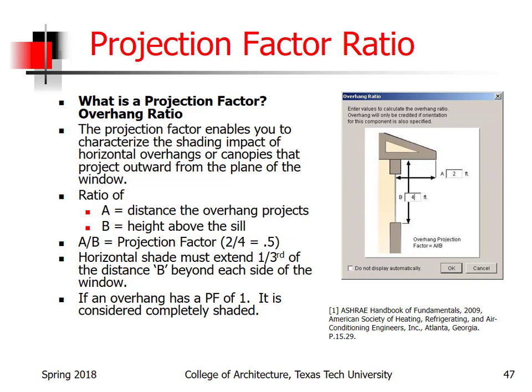And unless we can show we're using it in a way that will not cause that building to use more energy, then we're not going to be able to include that in our design. One way of increasing the amount of window on a building is to shade it, to provide shading for it. And of course, the simplest way to shade a window is some kind of overhang.